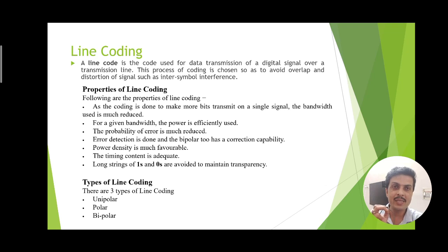And if there is a continuous fixed amount of voltage and thereafter there is a transition, then will the magnitude be pushed below the threshold or not? So there are so many queries regarding the transmission of binary bits. Such queries may be solved, that means such errors may be reduced, by means of a technique known as the line coding technique. This is nothing but the representation of binary bits by introducing special shapes of the electrical magnitudes.